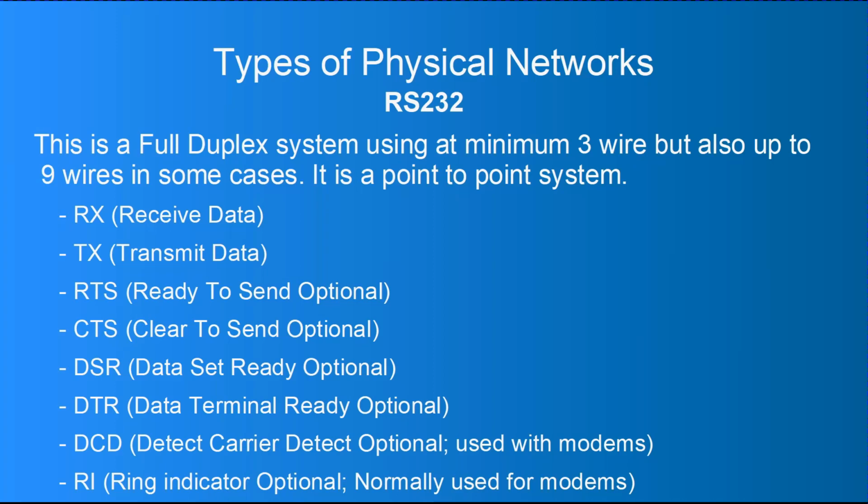Now, the other one that you may have heard of is TTL Serial, and TTL Serial is like RS232, except it's usually 5 volt logic levels, and the signaling is actually inverted by comparison. With the RS232, a logic 1 is transmitted as a 0 volt and a logic 0 as a 15 volt. Now, where I said the RS232 has a range of around about the 10 meter mark with our cabling, TTL logic is not even that. You're lucky to get a meter before you start getting a lot of interference on that one.